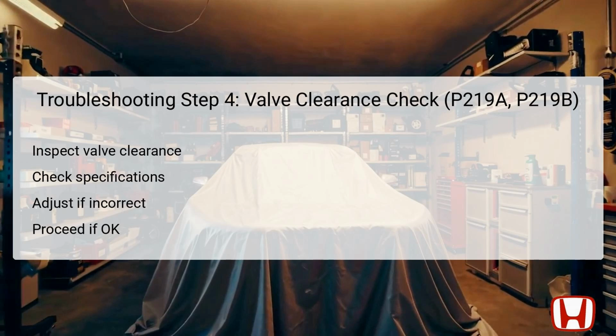In this step, you will inspect the valve clearance around the engine to compare it against specified values according to manufacturer guidelines. If the valve clearance is found to be out of specification, adjustment will be necessary to combat issues like poor engine performance or misfiring. After performing any required adjustments, if the valve clearance checks out as correct, you can progress to the following troubleshooting